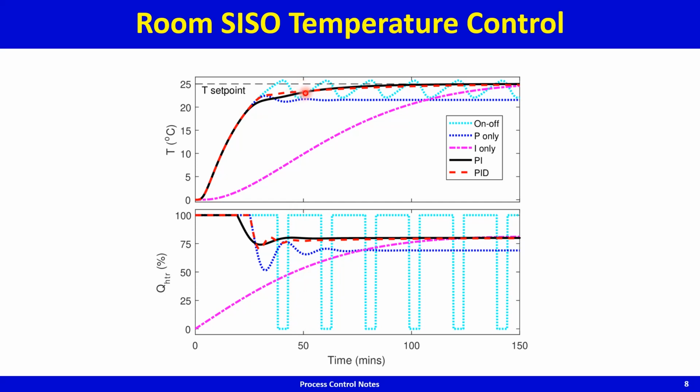The temperature continues to decrease before it turns back around because the heater has switched on, and then the temperature rises above set point, and the heater switches off. As the heater switches off, the increasing temperature turns around, decreases below set point, and the cycling continues. So if you use on-off control, you get this typical cycling behavior. The process variable is cycling, and the manipulated variable is bang bang, switching on, off, on, off. So bang bang control is on-off control.